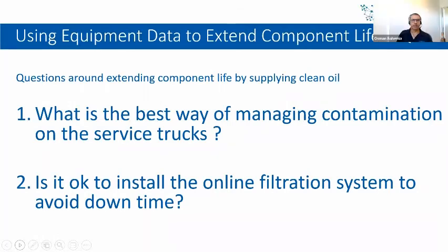Thanks, Angus. I think the point there is to make sure that you're checking the actual filters. Absolutely, yeah. They're commonly overlooked, and because they do such a fantastic job of cleaning the oil, they can hide those potential failures. You may fail a pump, or a component might fail with little to no warning when you have those systems. So always be aware, if you add something to a system, you need to understand those risks and potentially change your strategy or your condition monitoring checks to cover the risks you've now introduced.